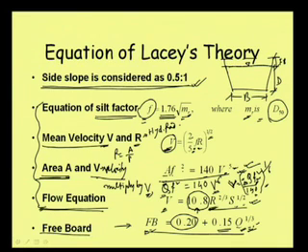Or we can go the other way also. Here it is r, and if we put r here, again the slope term is here, and what slope should we take? Once we get the v value, we can go back to the first formula, this one. As we have got v, we put v here, and by putting v here we can get the value of r, because f is already known. Getting that r, we can put r here and get what the slope should be, so that way we can indirectly calculate the advisable slope in that channel.